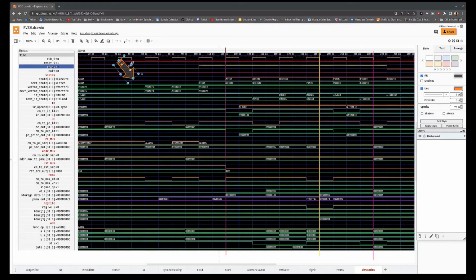So here we are at the timing diagram, and as you can see over here to the left, we have the reset sequence. This is what our processor does every time it comes up. We've covered that. The only difference is that our two x1 and x2 registers have been preloaded with 5 and 6, our two operands that we're going to operate on. And then x3 will be the output. Currently the initialize statement for that also has an 8 in it, so it has some value 8 that we placed in there.